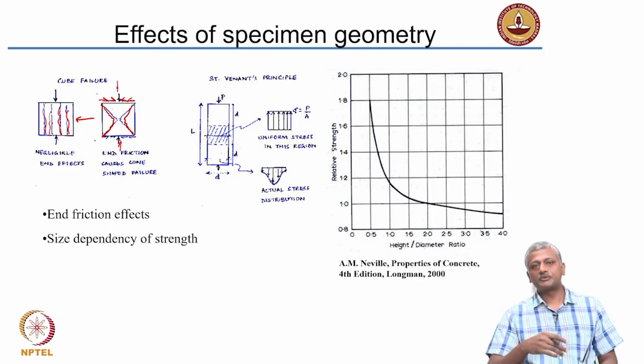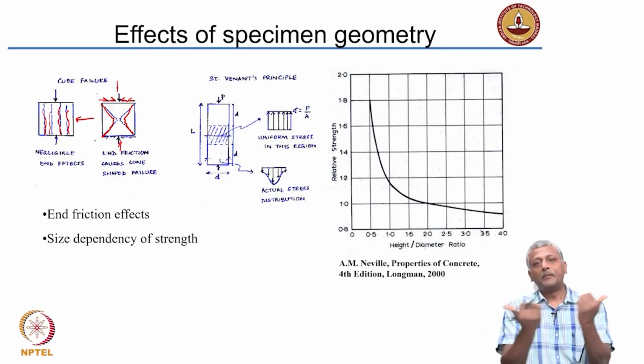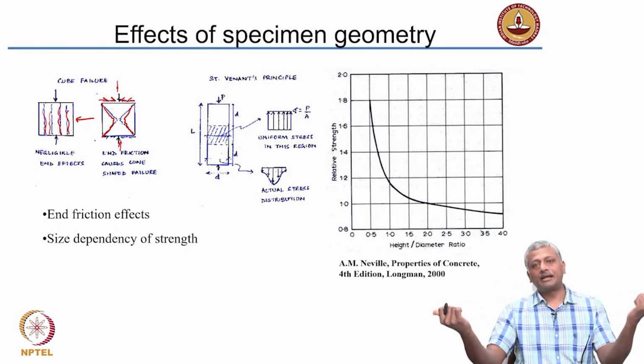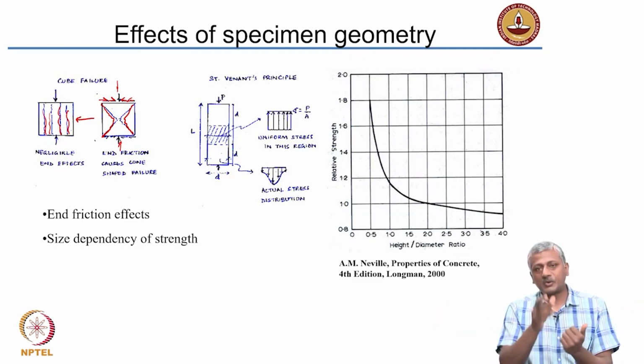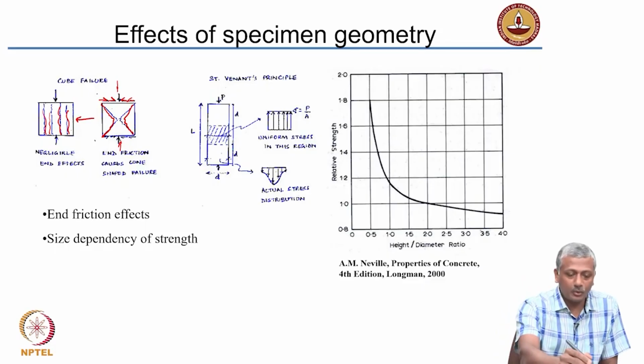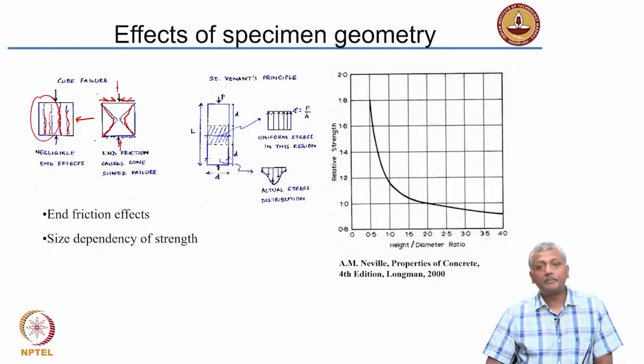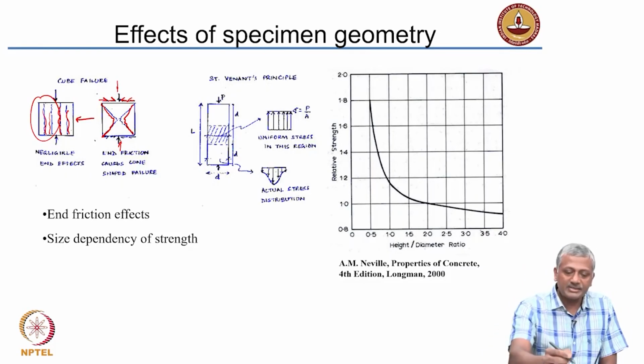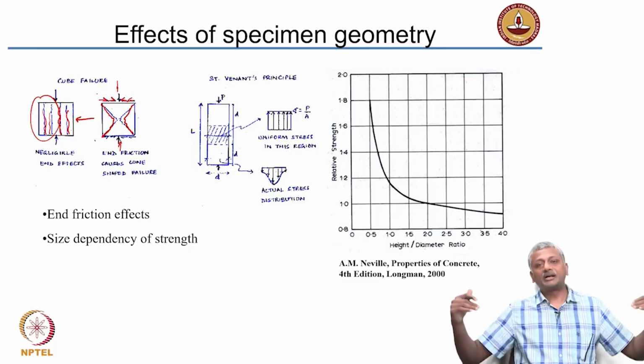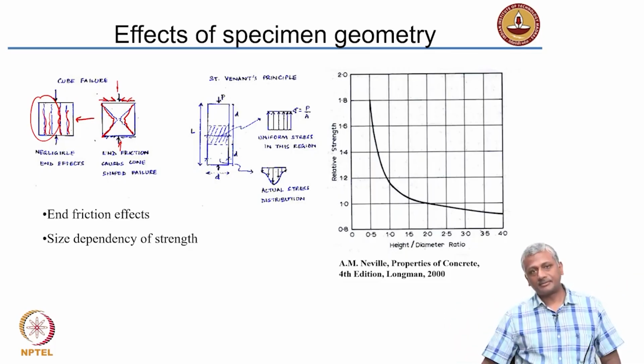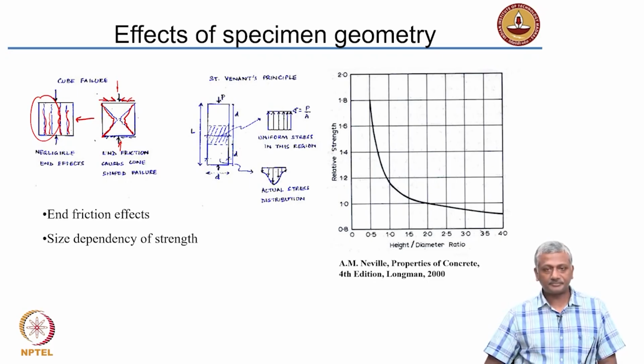What typically happens is that most materials that are compressed bulge out and exceed their lateral deformation capacity in tension, and that is why you get cracks parallel to the load. Of course, when you have friction, you start getting cracks that are inclined, because of the effect of the friction.